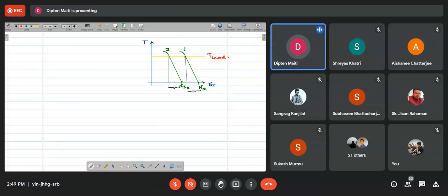Now, if the load torques are the same, this slip speed value and this slip speed value are the same. By symmetry, this line is equal to this line because these are the same load torque, and further this part is equal to this part, because the torque being the same, we have the same amount of slip speed required. So the two triangles that can be seen here are congruent to each other.